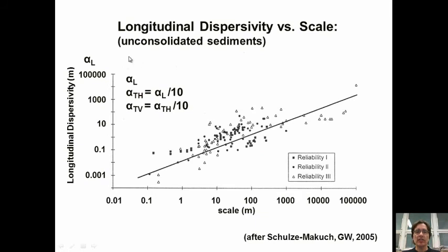How do we define these dispersivities for our given site? Well, if we don't have any existing plume, our system is clean, we can base our dispersivities, first of all, on the scale of our system. So here's some data from a paper by Schulze-Makuch showing the longitudinal dispersivity alpha L versus system scale on a log scale. So here, for instance, if our maximum plume extent is going to be 100 meters, we can use this kind of graph to estimate a longitudinal dispersivity of, say, 1 meter.